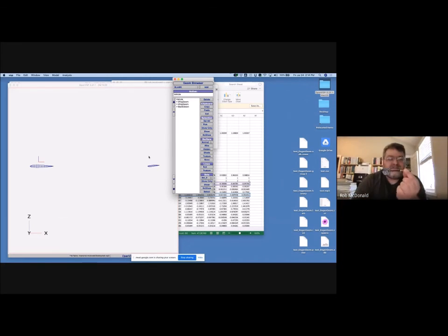But it tells you that to have a stable airplane, you need the tail in the back and the weight somewhere up in the front. And what it doesn't tell you, the reason I said a dart's a really bad airplane, is imagine, the purpose of a wing is to get lift equal to weight, right? We need an upward force, a lift, to counteract the downward force. So if we want to get lift to counteract the weight, the only thing I have to do lift is these tail surfaces. So imagine if I put a whole bunch of lift back here, how do I counteract that weight vector? I can't. So the tail is great for stabilizing the airplane, but to make a dart into an airplane, let me